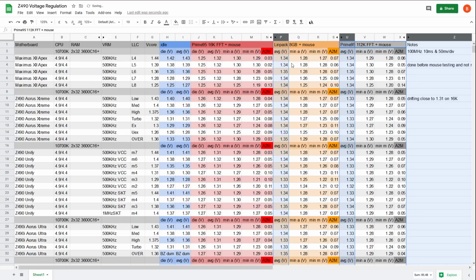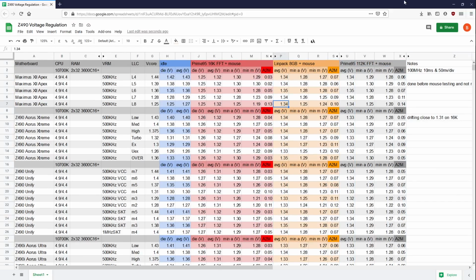Well, the funny thing is, if your VRM also has a ridiculous amount of overshoot, then the controller is going to struggle to regulate the voltage going to the chip. The reason that would be concerning is not because of the actual overshoot level. It's concerning because it can lead to excessive undershoot. The controller is going to see the excessive overshoot and start trying to compensate for that. And if the CPU suddenly goes right back into pulling a ton of current out of nowhere, then the VRM might still be trying to compensate for a bunch of overshoot while the CPU is ramping up to full current draw, and so you get excessive undershoot after that, and that causes further instability on the CPU.